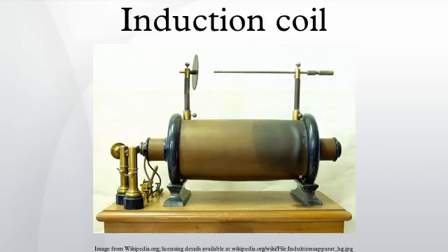Construction details. To prevent the high voltages generated in the coil from breaking down the thin insulation and arcing between the secondary wires, the secondary coil uses special construction so as to avoid having wires carrying large voltage differences lying next to each other. In one widely used technique, the secondary coil is wound in many thin flat pancake-shaped sections, connected in series. The primary coil is first wound on the iron core, and insulated from the secondary with a thick paper or rubber coating. Then each secondary subcoil is connected to the coil next to it, and slid onto the iron core, insulated from adjoining coils with waxed cardboard discs.